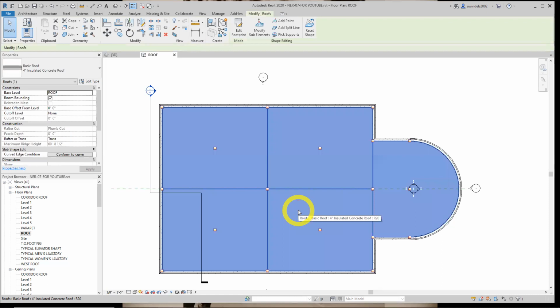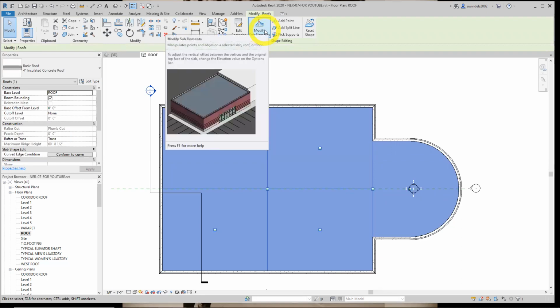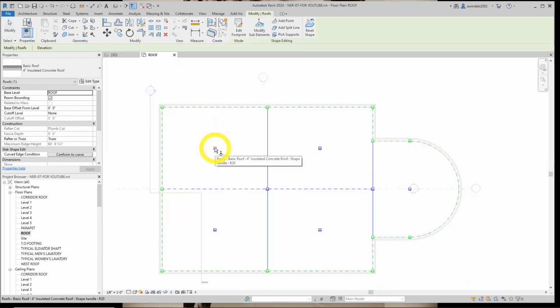Selecting the roof, we're going to go to the modify sub elements. This is a new command for us, and this would have helped us a little bit to know a little bit more on the floor chapter to modify these points particularly. And we're going to add elevation of -3 inches to all of them. So we hit it once, still got our icon of the little cone there, and then we'll type 0 space 3. My mistake, -0 space 3. Want it to be a drainage scenario. So we want this to be our most downhill spot.